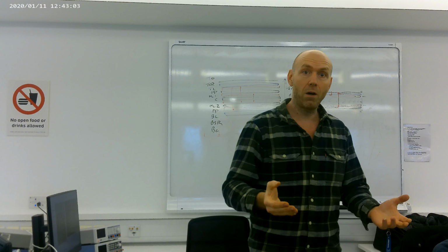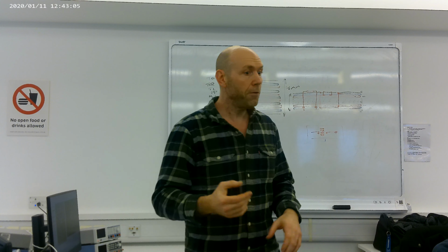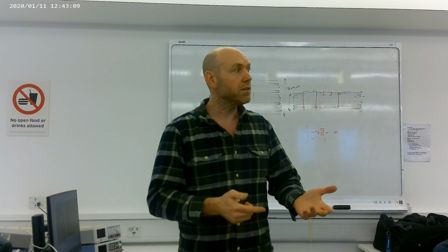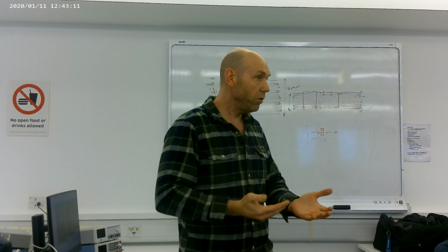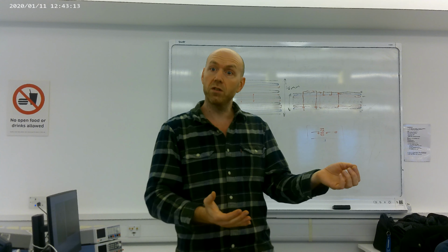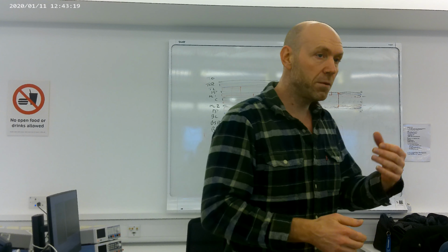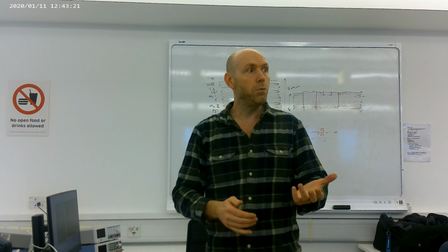Understand as well what your tracks are doing. If you've got one power feed that's feeding a motor, for example, that's going to take a lot more current through that trace than one that's just signalling something as an input. Yeah? So you would make that track thicker, and if it was particularly large, then you would want to understand